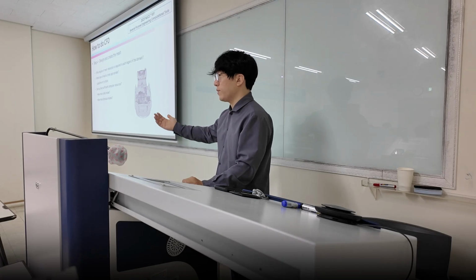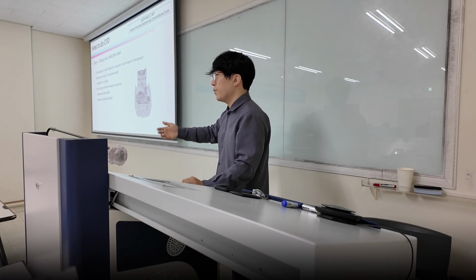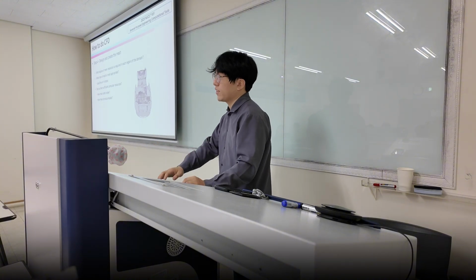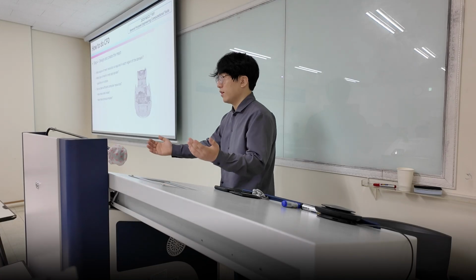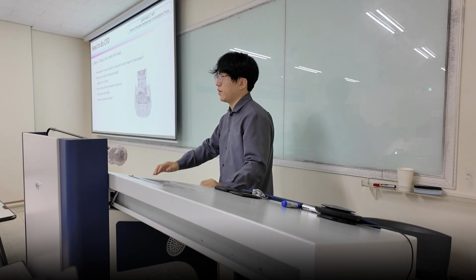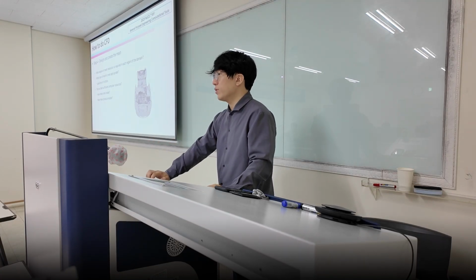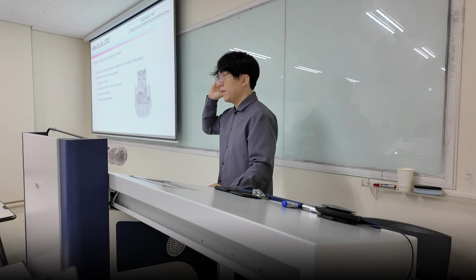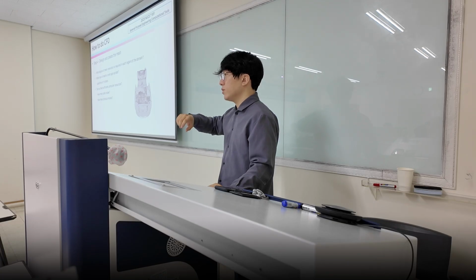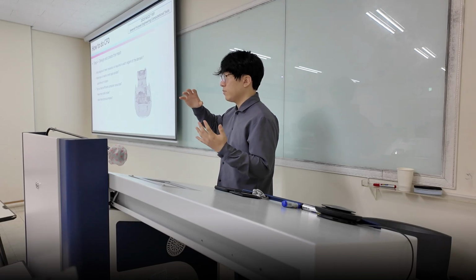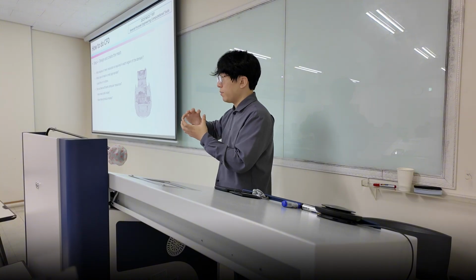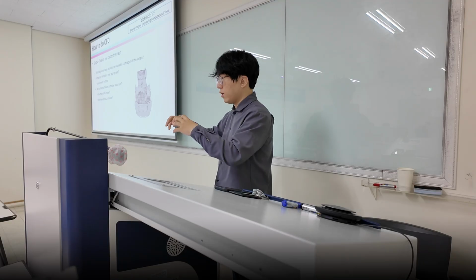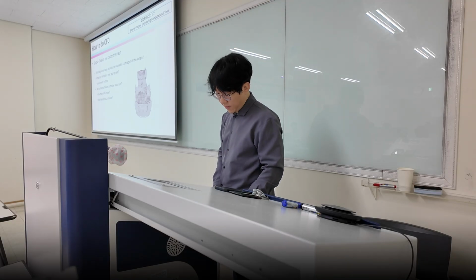You're gonna run a numerical analysis, and then 3 months later, you're gonna check the result, and you're gonna see, oh, it didn't go well, so you're gonna run it again. And then if you do it 3 times, you basically waste a year. So it's really important to assess the time it takes really carefully, and then try with simplified models first, and then try with smaller number of mesh, and then increase the resolution and adopt more complexity to it.